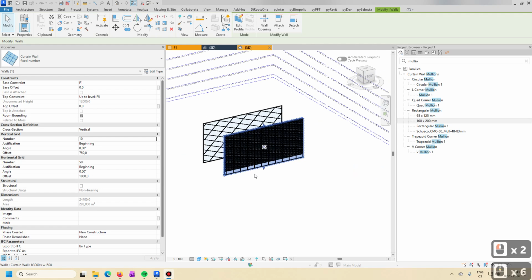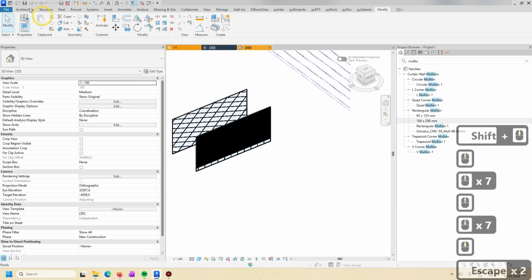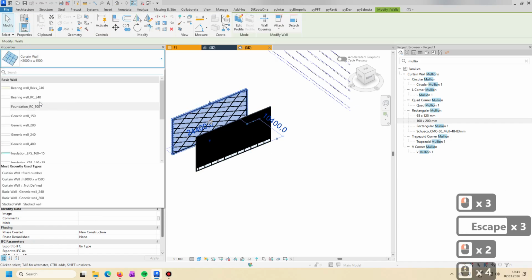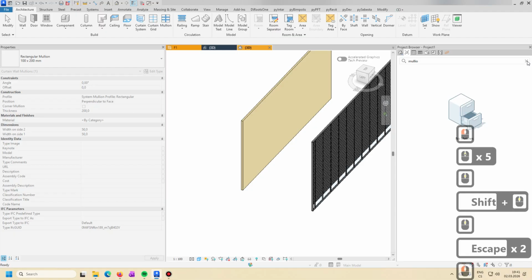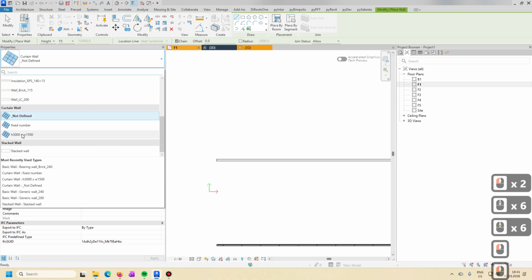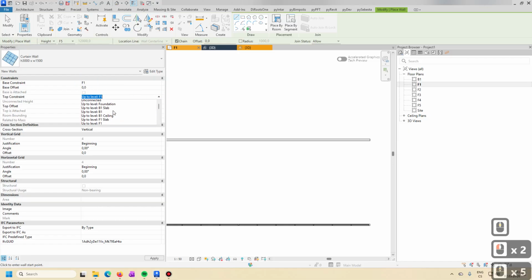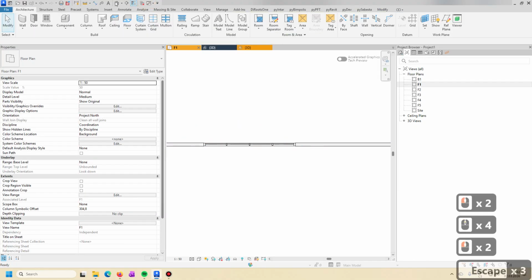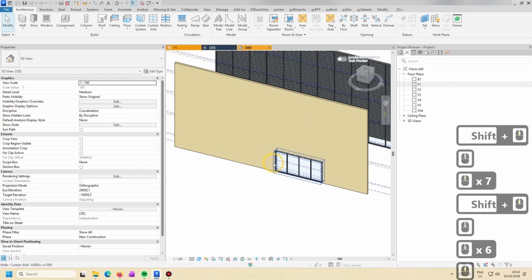And the last thing I want to do is to show you how to create the embedded curtain wall. So let's create a regular wall. Or we can change this one so it's a regular wall. So we have a regular brick wall, and when we go to the floor plan, we can select this one that we created before. We want to go from F1 to F2, for example. We start here and there, and if you go to 3D, you can see that it automatically created an opening in the wall.